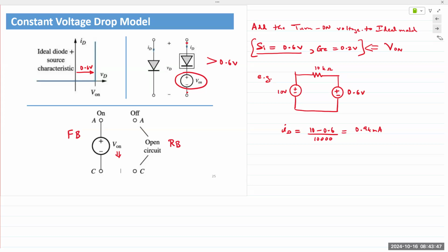If we don't need a specific voltage or current value, we just need to know whether, say, a switch at the end of the circuit is open or closed, then we just use the ideal diode model: on, off, on, off, and then the output is most likely on or most likely off. But if we need a specific voltage or current, then we perform a more accurate analysis.